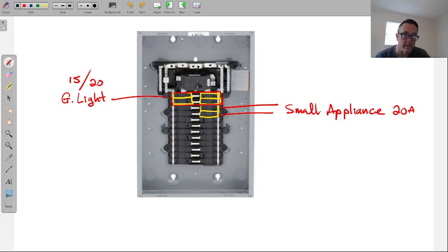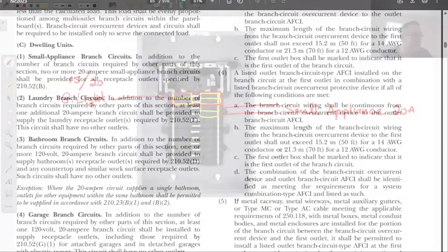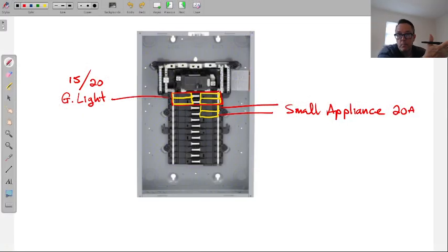This is why it's important, while it is a big expense, to update your electronics every 5 years, I would say, because you're just wasting more electricity now. So while we are now including an EV car charger, again, keep in mind, a person might not have an electric vehicle, the code is now requiring them in houses. Building codes in areas are requiring them as well. So we are adding amperage to panels, and most average homes now are getting about 200 amps. Whereas it used to be about 100, or like that 2-story house that I showed you was just a 150. These days, that would be 200, 300 amps.